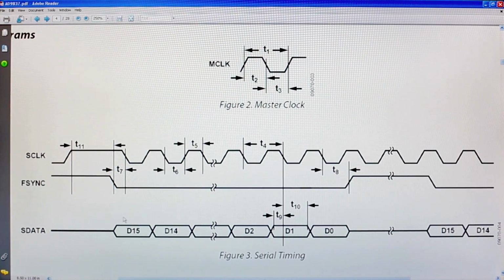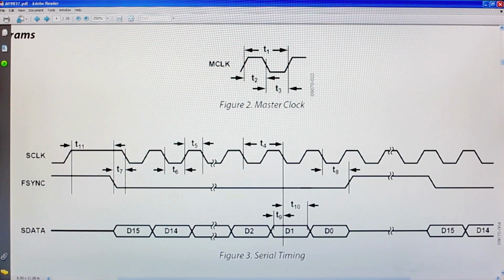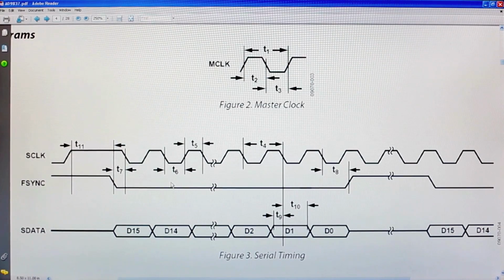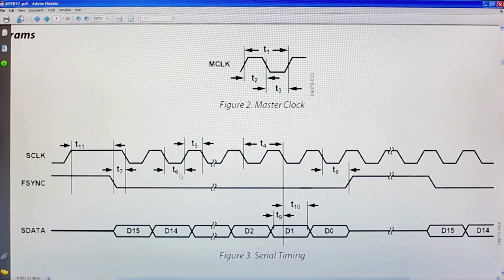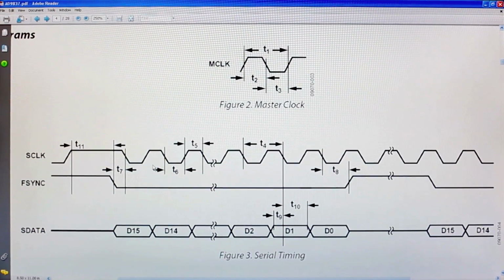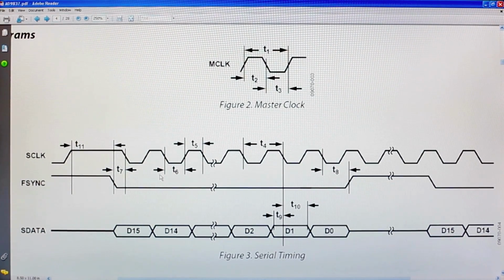And for that reason, the hardware does not fully commandeer use of a select line, because they know you're going to have to adjust those timings. So you have control of the select line manually in most cases. And then there's the S clock. Depending on the part you're trying to talk to, you can set it up to read data on the low-going edge or on the high-going edge. Like I say, the standard is very, very loose.